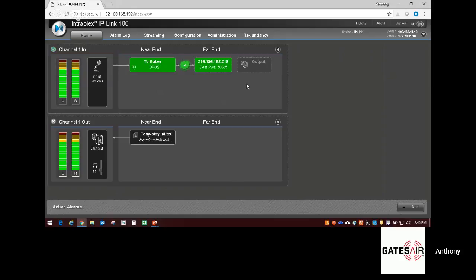He also points out that they have one IP 200 that's feeding about 7 IP 100s. So there's some flexibility that you can power with. Yeah, and again, whether it's an IP 200 or an IP 100 or a 100p, it's just how many channels you're getting and the functionality. If he's using a 200 for multiple paths out, you can send them to 100s. They're fully compatible. The only thing that's not really compatible are the Mpx series. You need Mpx on both ends in order to transport the composite back and forth. But if you're doing a 200 on one end and 100s, that's not a problem at all.